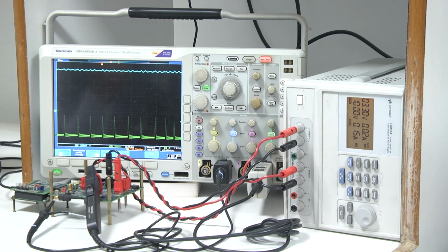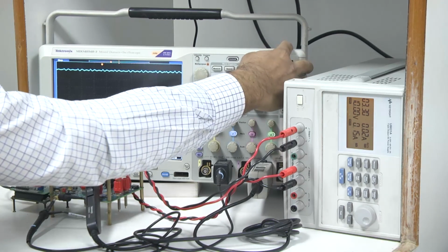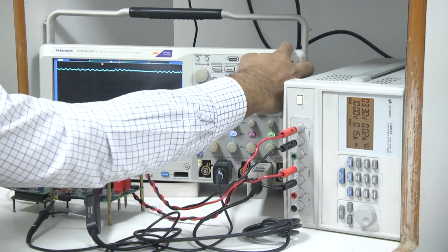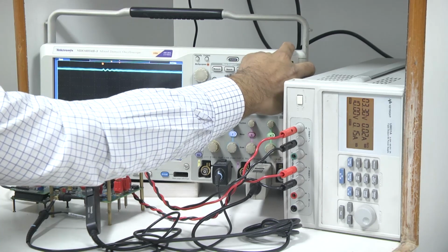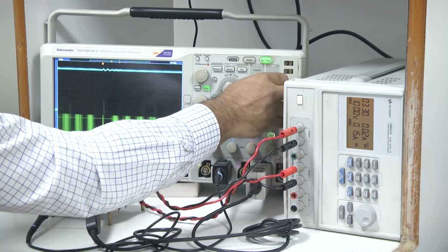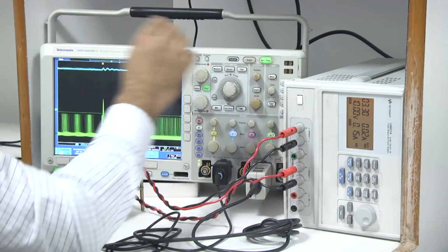But we have discussed that since there is a sampling time of 40 nanoseconds, there is a mismatch because your effective time period is not an integral multiple of 40 nanoseconds. As a result, there is always some quantization effect and a jitter effect, and that is actually coming here. But this large spike which is coming is still there.